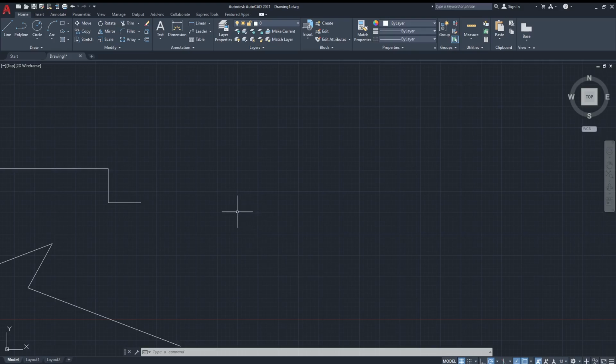You will be able to just click L, choose a starting point. As you can see, if you press Enter, you'll choose a starting point right from the previous point you went to. So we will not be doing that actually. Let me press L. I'll choose a starting point here. This is the only place where I will be using a mouse. I'll be using 20 as a length, and in this case it'll be 0.